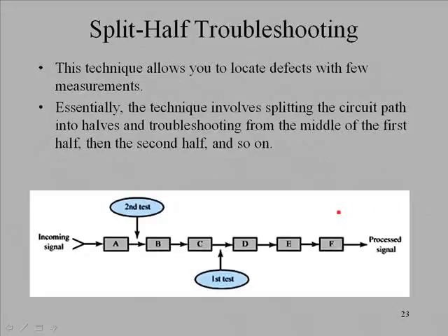Split half troubleshooting. This technique allows you to locate defects with a few measurements. Essentially, the technique involves splitting the circuit path into halves and troubleshooting from the middle of the first half, then the second half, and so on.